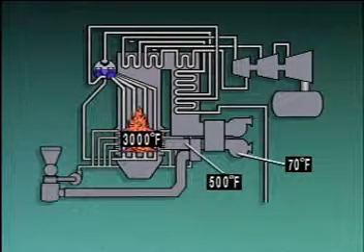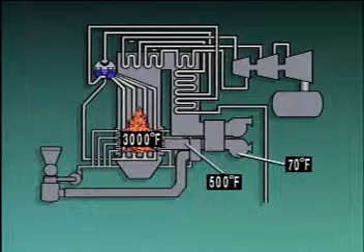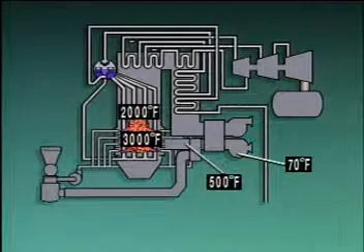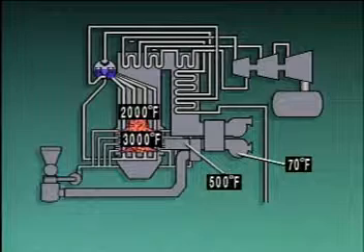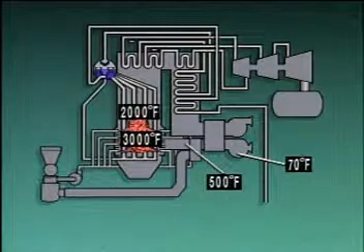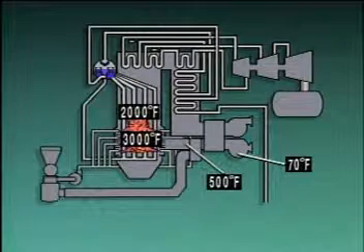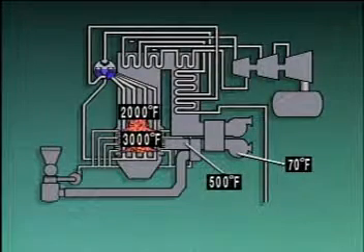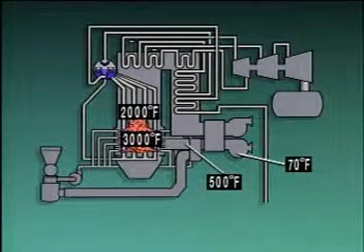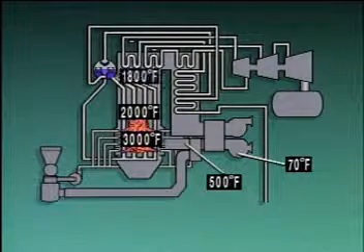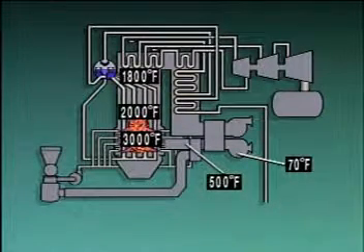As the combustion gases rise in the boiler furnace, their temperature decreases to about 2,000 degrees Fahrenheit as heat is absorbed by the tubes surrounding the furnace. By the time the combustion gases enter the area of the gas flow path that contains sections of boiler tubes called superheaters and reheaters, their temperature has dropped to about 1,800 degrees Fahrenheit.